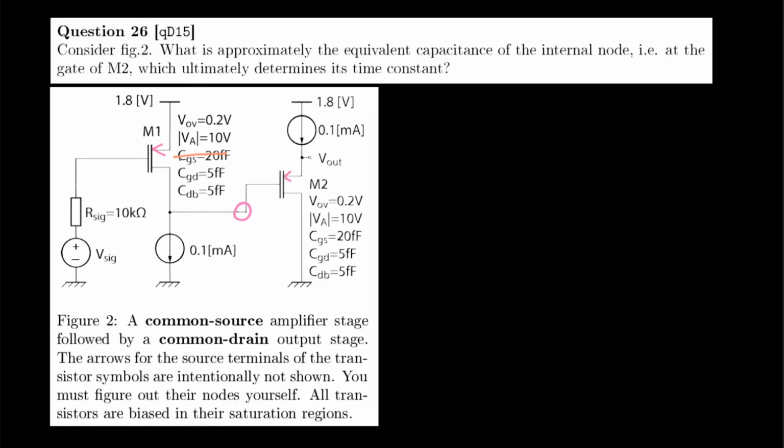In this figure it's not given explicitly to which voltage the bulk is connected, but typically it's connected to a high voltage, so in this case VDD, for a PMOS transistor. So in a small signal equivalent, CdB is connected between the drain and a small signal ground, and therefore it contributes to the time constant of the internal node.